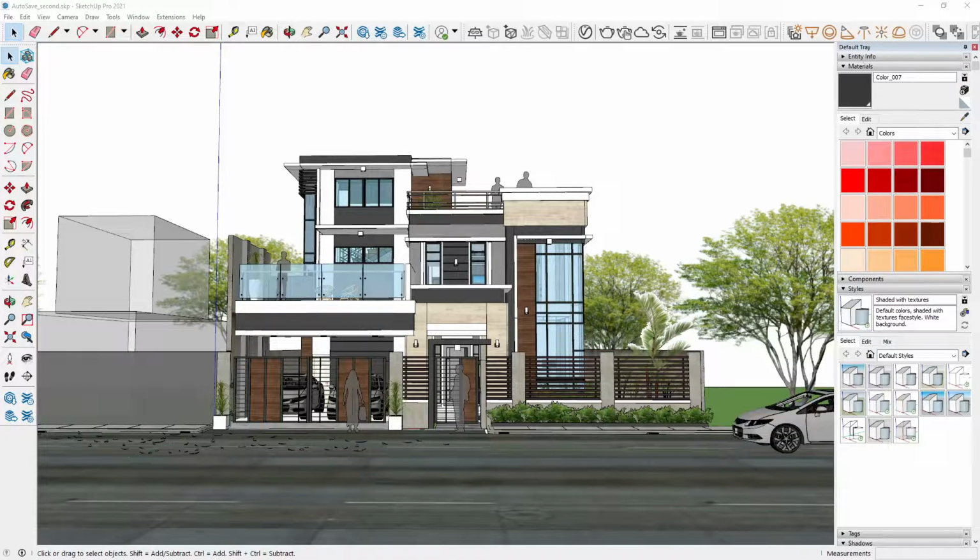So buildings are rarely a simple rectangular shape in plan. So a typical elevation may show all parts of the building that are seen from a particular direction. So geometrically, an elevation is a horizontal orthographic projection of a building onto a vertical plane. So the vertical plane is normally parallel to one side of the building. So architects also use the word elevation as a synonym for facade. So the north elevation is the north facing wall of the building.